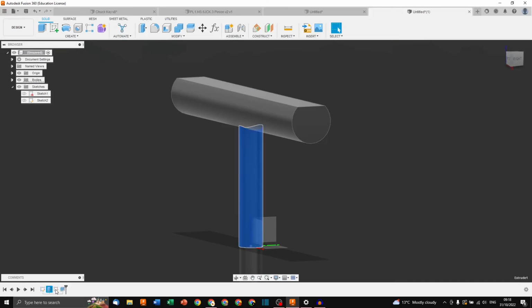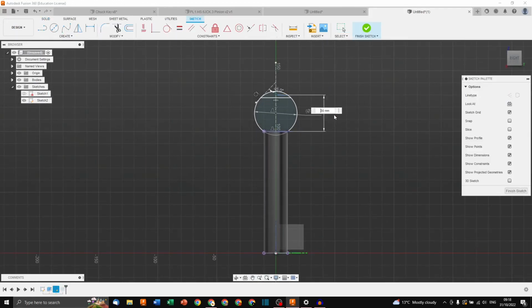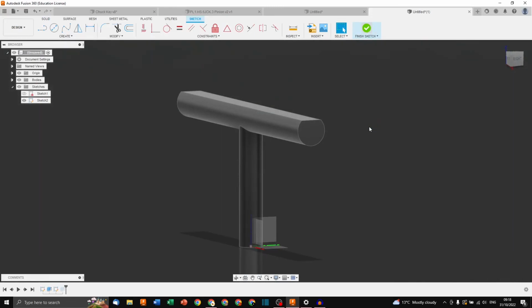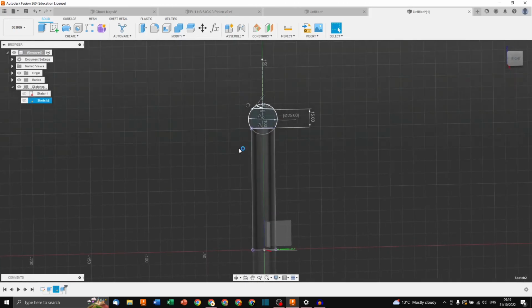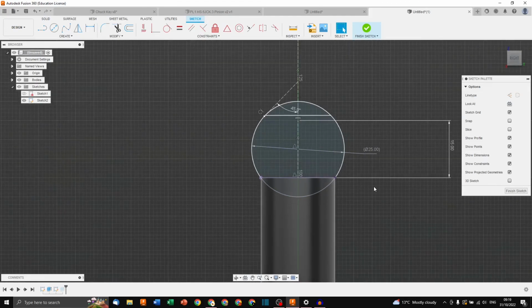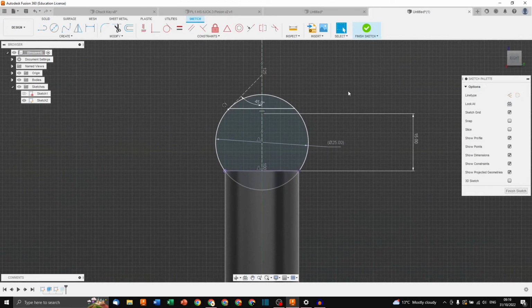So you can imagine that if you were to do this in a model that's very long and takes hours to make, and that you work with 5 engineers on, and somebody at the beginning of the model history made a crappy sketch, and you realize that you need to change one dimension from it, but a week later, and 5 people have worked on his work and taken his sketch as a base sketch to draw their own work on, now you'll break 15 people's work for a week by having made a crappy sketch. So please make good sketches that are fully constrained, and it's going to help you and your team a lot and save you a lot of time.